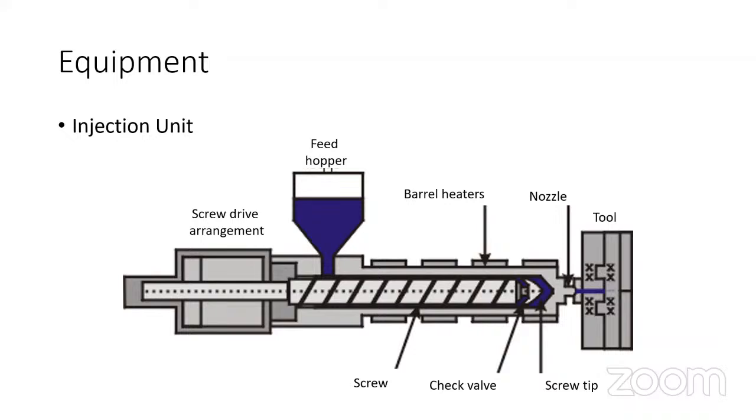Now, friends, both these units are very important. Now, very important is that the clamping pressure should be higher than the injection pressure.